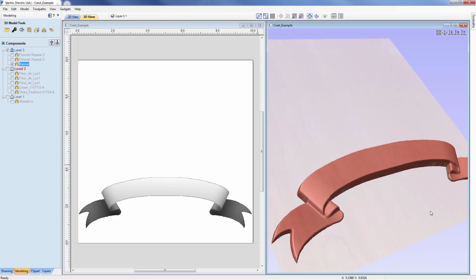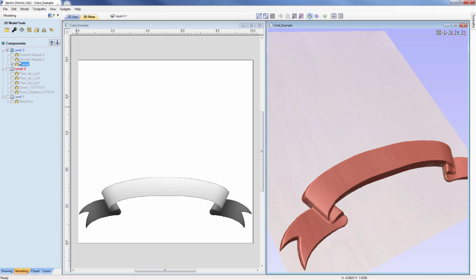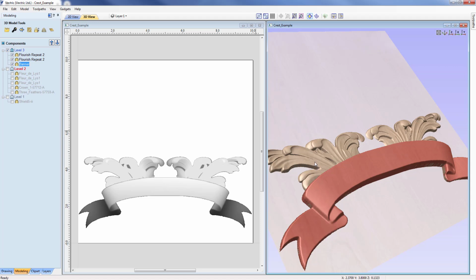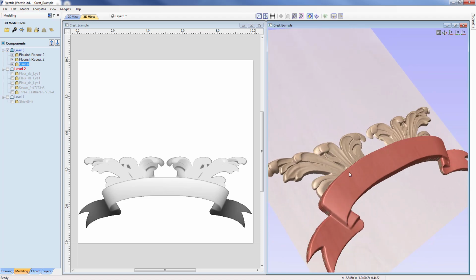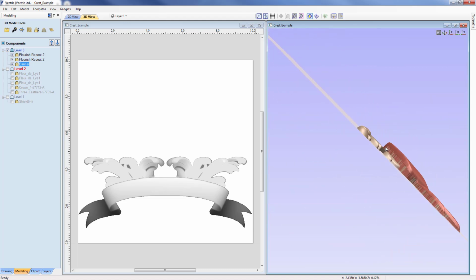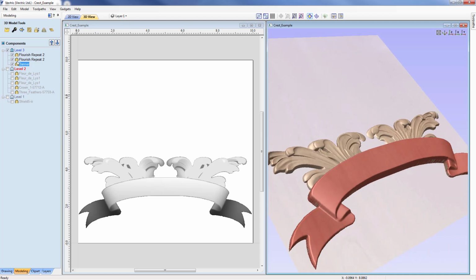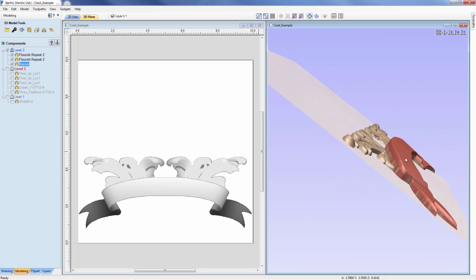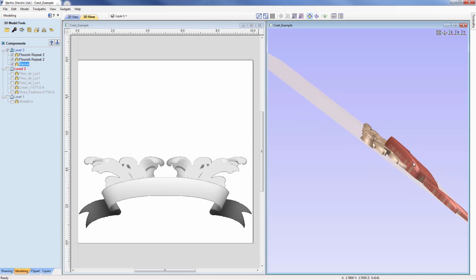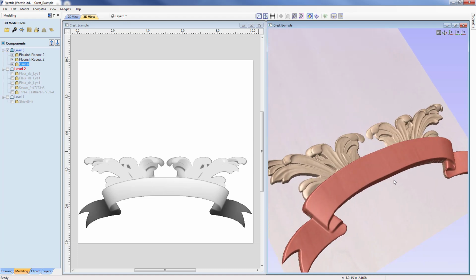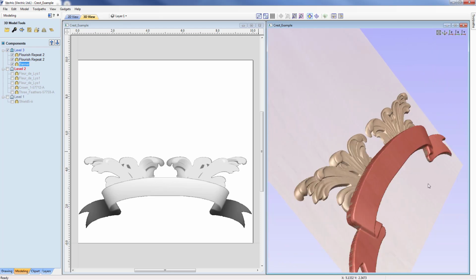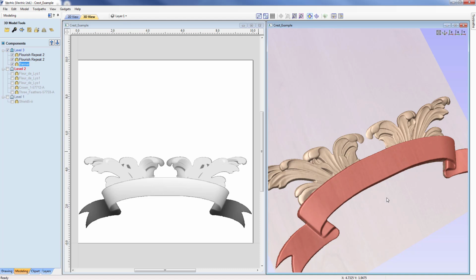And what we want to do is to understand really how it interacts with the other 2 items on that level. So I'm going to switch on the 2 other flourishes, and we can see that the base of them disappears underneath the banner here, because the banner is much deeper, and because the combine mode of the flourishes is set to merge. Okay, and that means that the highest value is being kept, and in this case the banner is the highest value, so that's the bit we see, and in essence the flourishes are just sort of disappearing behind that banner.